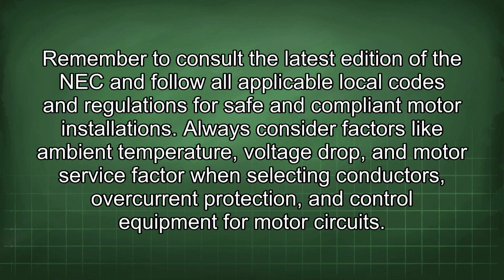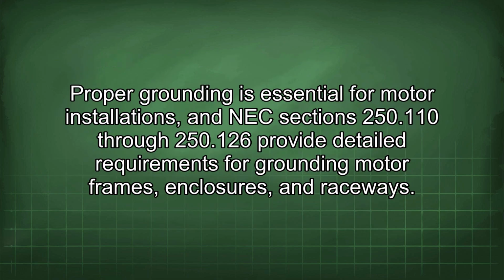Remember to consult the latest edition of the NEC and follow all applicable local codes and regulations for safe and compliant motor installations. Always consider factors like ambient temperature, voltage drop, and motor service factor when selecting conductors, overcurrent protection, and control equipment for motor circuits. Proper grounding is essential for motor installations, and NEC sections 250.110 through 250.126 provide detailed requirements for grounding motor frames, enclosures, and raceways.